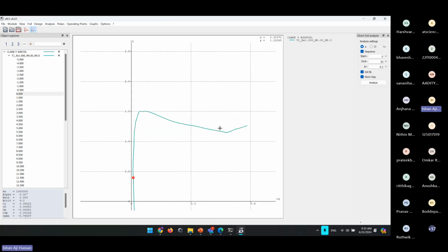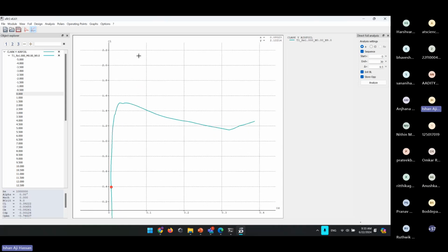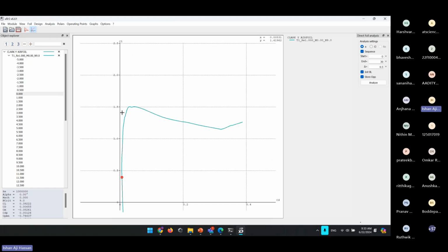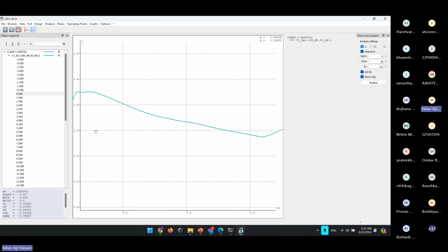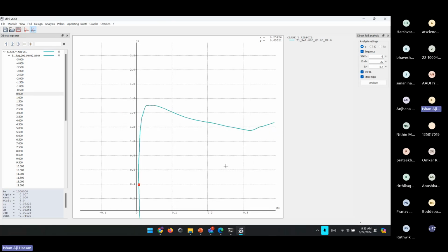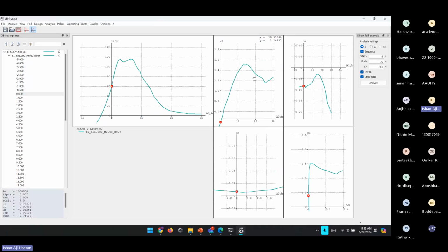And this decline here is basically afterwards. So this also you can explain by looking at the other graphs. Here essentially for a range of CL from 1.5, I believe, to 1.2, you're getting such a large range of CDs. That is also basically for a CL range from 1.5 to 1.2, that basically means this whole stall region. From 1.5 to 1.2, you're operating over an angle of attack range of almost 7 degrees to 25 degrees or so.